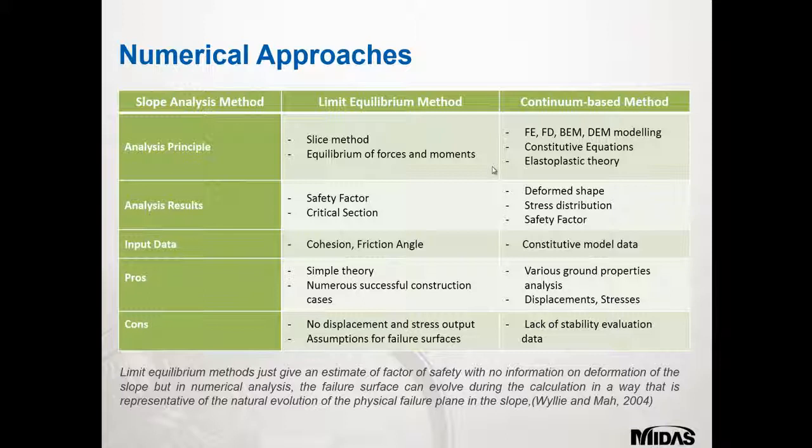So just the different numerical approaches. The main difference between the limit equilibrium method and the continuum based method are highlighted. The limit equilibrium solves a problem using statics by dividing the slope into a multitude of different slices, whereas continuum based methods involve more detailed behaviour using FE, FD, BEM or DEM methods.